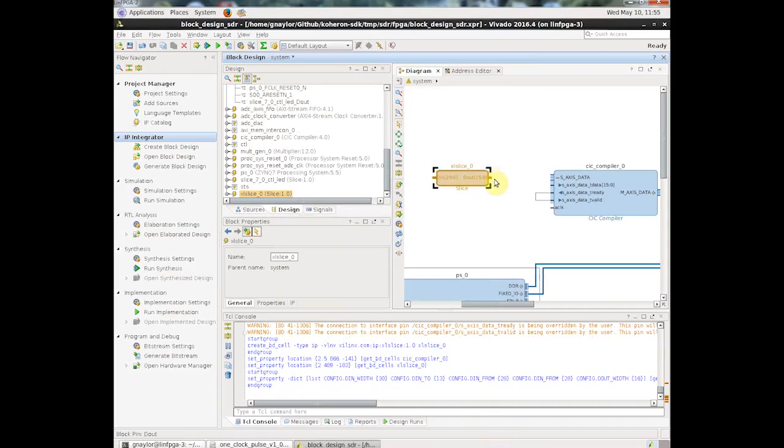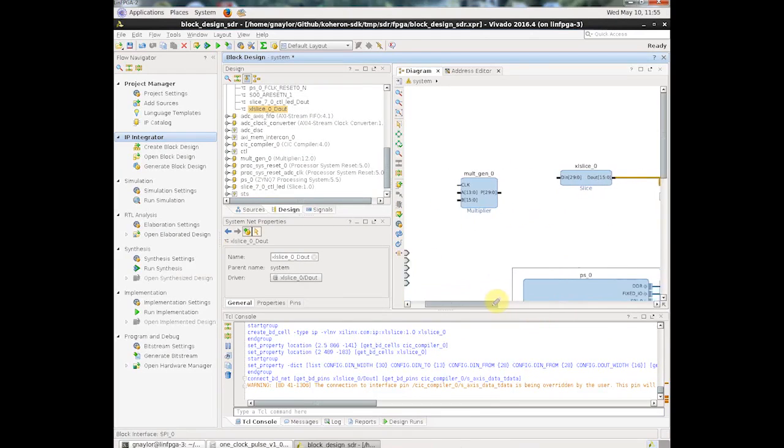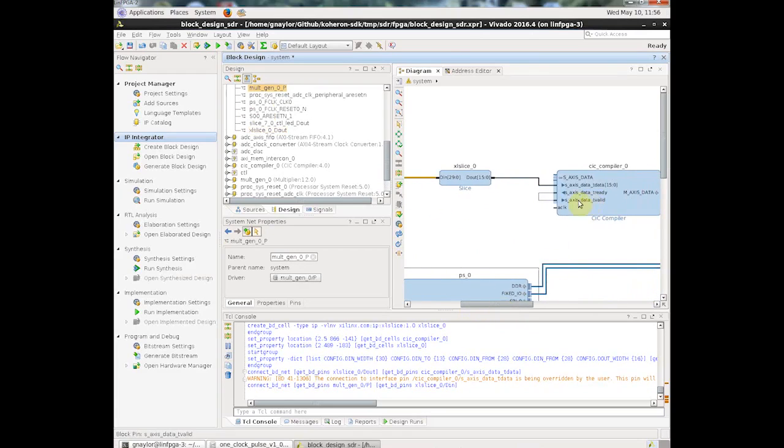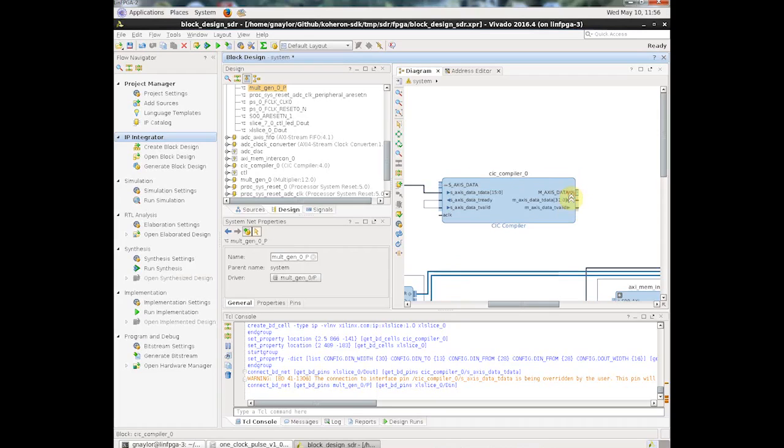Okay. We'll put that into the data input, and we'll take the data from the multiplier, and as I say, the T-valid is going to be held continuously high because every clock cycle the data is going to be valid for the input, but it's going to be decimated significantly at the output, so we're going to need to use T-valid at the output of this block.